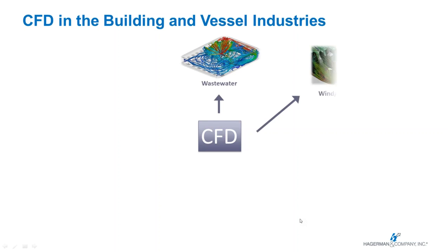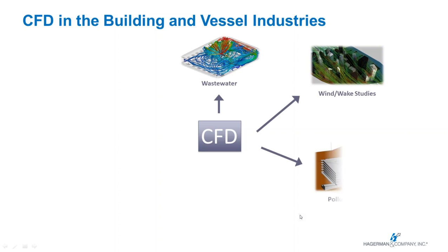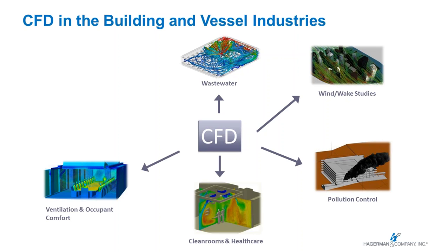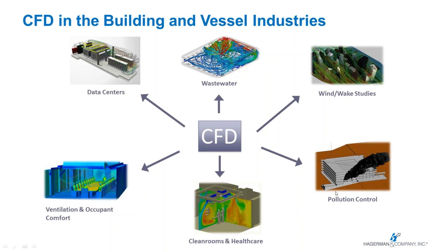CFD applies to the wastewater industry. We can do wind and wake studies. We can look at pollution control, making sure that emissions from a building don't get entrained back into the building. Or imagine a helicopter on top of this building, and you've got HVAC ducts on the top there. Do the helicopter fumes get entrained into the main airflow? We'll look at clean rooms and healthcare, ventilation and occupancy comfort, and also data centers.